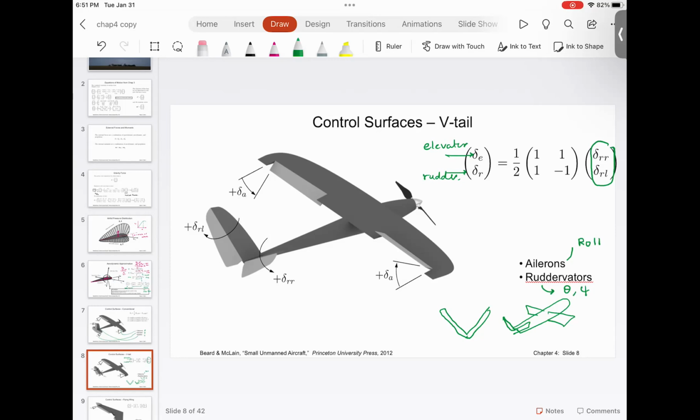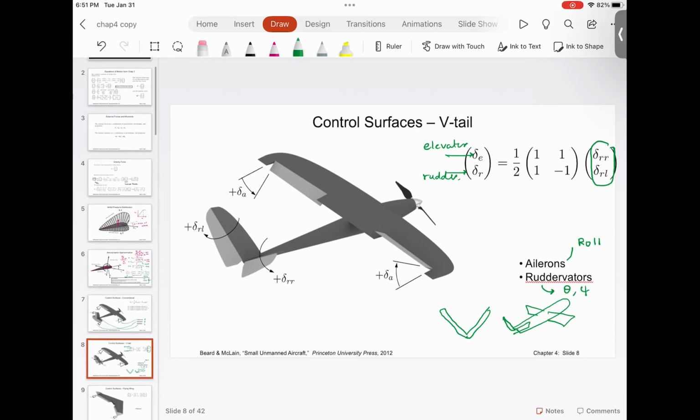Everyone understood this? Doesn't this combined structure, this rudder, have some component in the roll direction also, right? The roll direction is taken care of by the aileron. The rudder doesn't have any effect in the roll direction. Actually, let me put it this way. Whenever you have a deflection of the control surfaces, the aerodynamic forces are actually coupled. So there will be some effect, but the majority of the roll control is done by the ailerons.